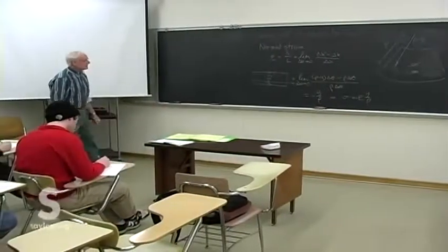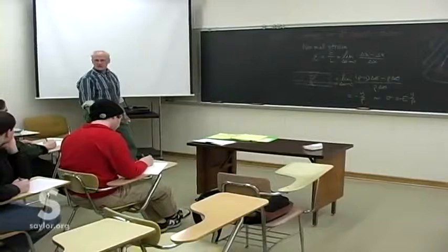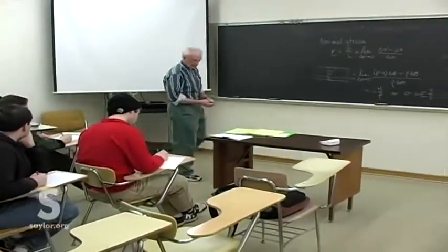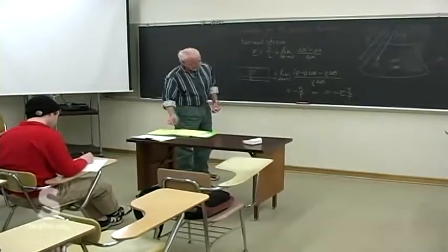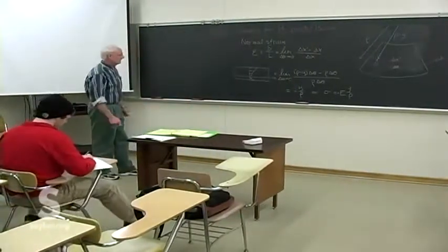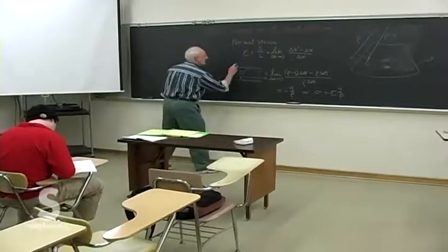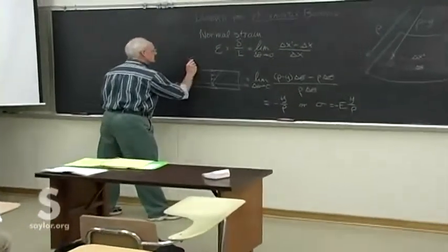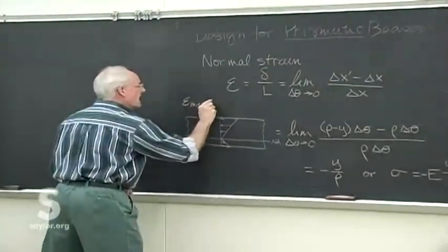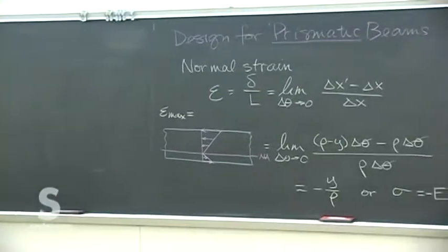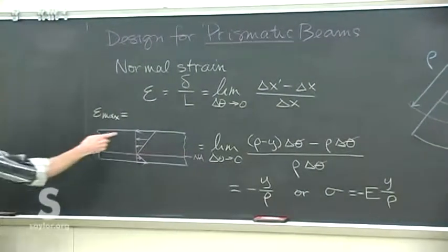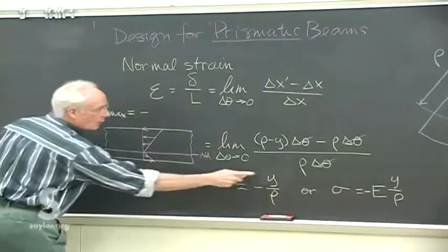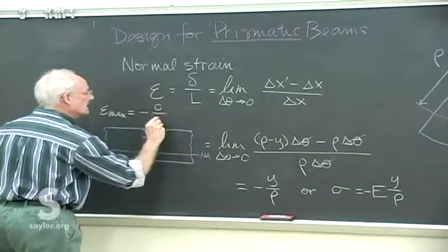So for the bending shown, we have linearly varying compression on the top half, well, I say half in quotes because I don't know where this neutral axis is yet. That's our next job. We can also say that at the extremes, the maximum strain is at this very top surface up here, and that's not at y, but at c.